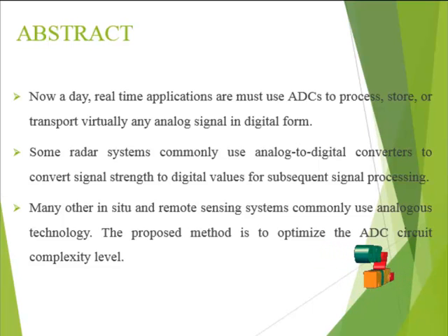Since the pipeline ADC eases the significant cap DAC loading and comparator noise, it would be a good candidate for low voltage and fine resolution applications. Research on the pipeline ADC has mainly focused on the design of operational amplifiers. As CMOS technology scales down, the design of a robust high gain op-amp becomes increasingly difficult due to the low device gain.